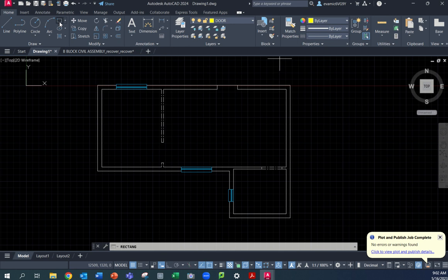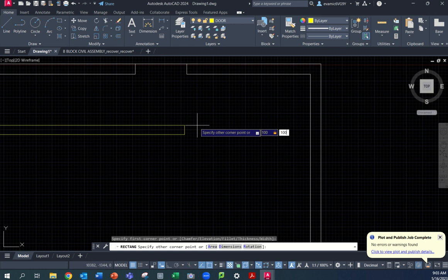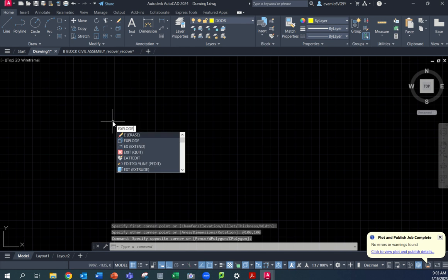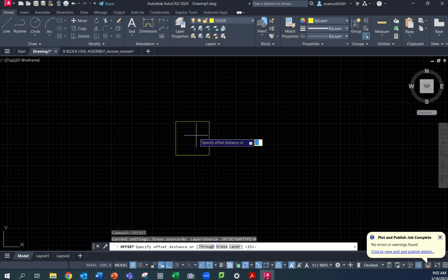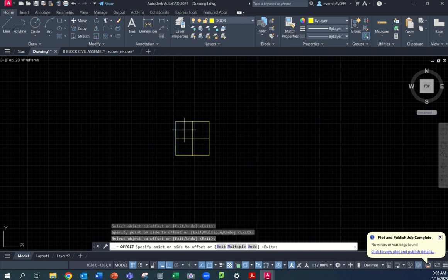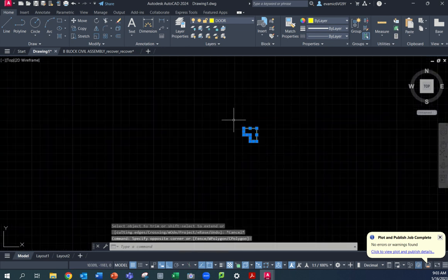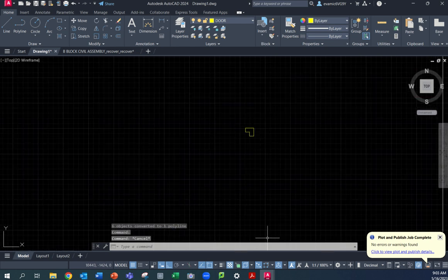So I'm going to use a little block here, 100 by 100, and I'll do this quite quickly. I'll just draw inside, it's fine, 100 by 100, enter, there's the block. I'm going to explode the edges so I can select them individually, and I'm going to offset by 50 on the edges that I need to. So I'm going to bring this in 50, and I'm going to bring this in 50, right? There we go. Take my trimmer, and I should be able to trim accordingly, and I've created the spec for my door frame. Now I'm going to go join, highlight, join, enter, and I should now have made the spec exactly what it needs to be.